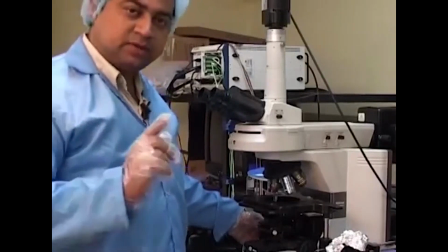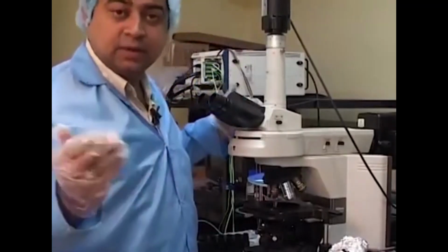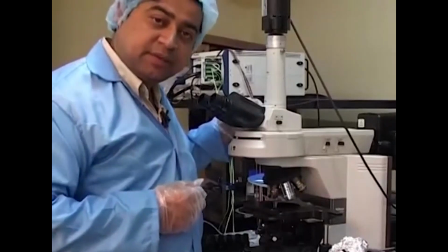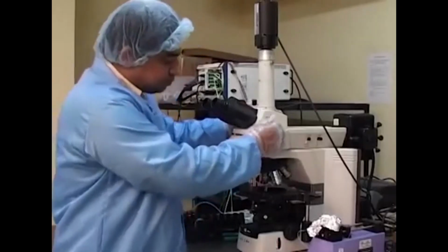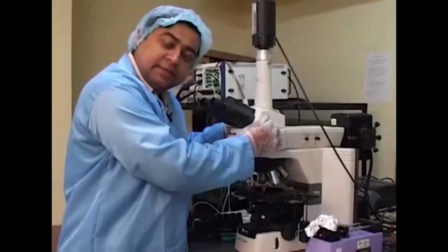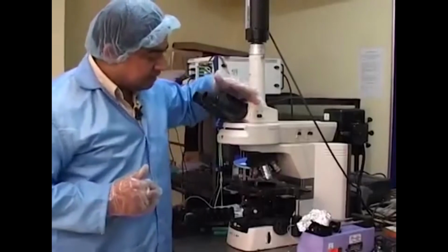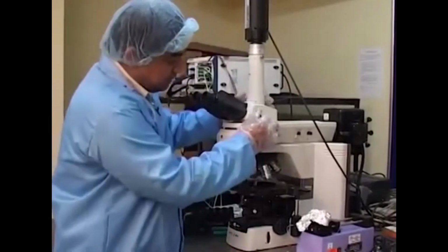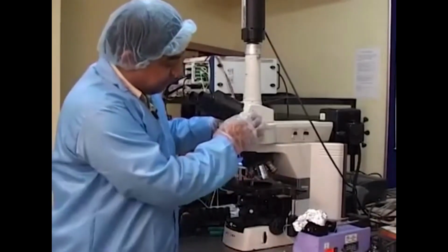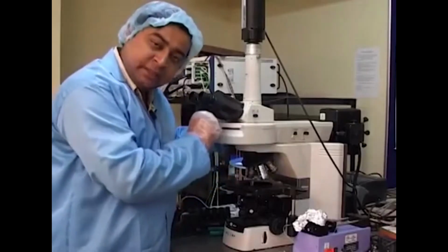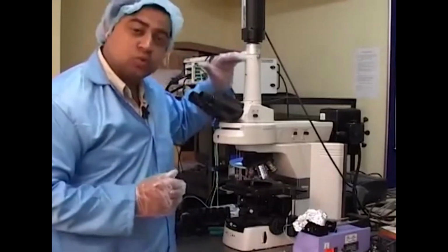Okay. Now I am going to transmit and use the CCD camera to acquire what is there for your benefit, so that you can see what we did in our last experiment on photolithography. For that, what we need is to use this lever to open the shutter for this particular camera. Now there are 3 options in this lever, and this lever can come out and go back in. When the lever is in its inward position, it only exposes the eyepiece and you can only see the image, but you cannot see it through the CCD camera.